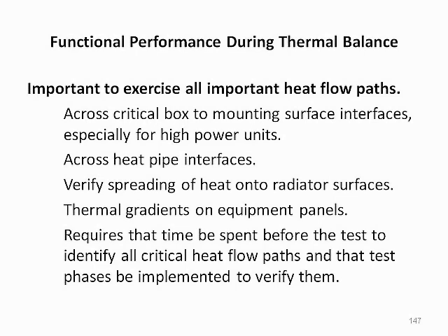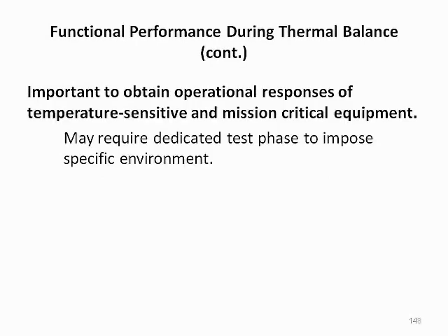Success requires that time be spent before the test identifying all critical heat flow paths, and that the test phases are implemented to verify them. It is important to obtain operational response data for temperature-sensitive and mission-critical equipment. This may require a dedicated test phase to impose specific environmental conditions.